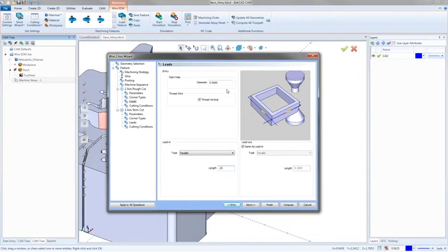But there's a button here that you can handle more things with. In the bottom left-hand corner of this box, there's a button called Apply to All Operations. It's there all the time. A lot of people never even notice this button. If you're one of those guys, leave me a comment, because a lot of guys don't ever see this button. What this lets you do is copy your pages so you don't have to do them over and over again. It's real handy when you're doing a whole bunch of lead-in pages and corner types and really anything that you can copy from one cut to the next.